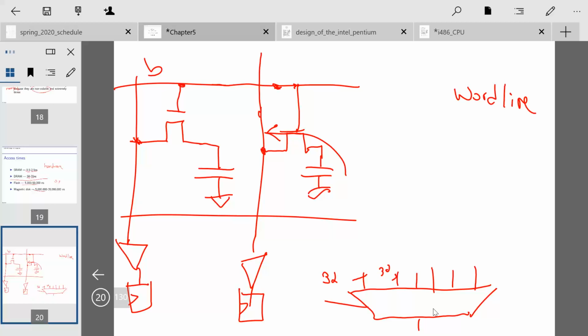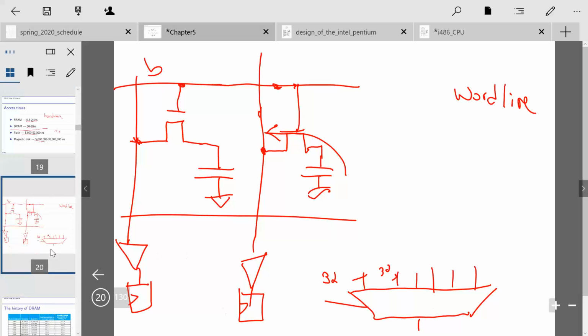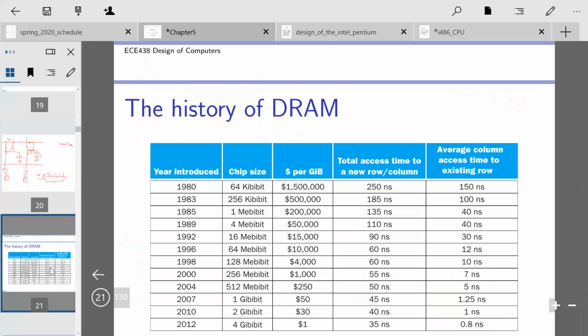So after we read the contents from DRAM, we have to write it back, and your DRAM controller handles all of that. Then of course we have to have a periodic refresh, which just goes along and sequentially reads a row and writes it back. I just wanted to remind you, since we talked about this stuff early on in the semester and then jumped into pipelining and everything else, so I wanted to refresh your memory of how that works.